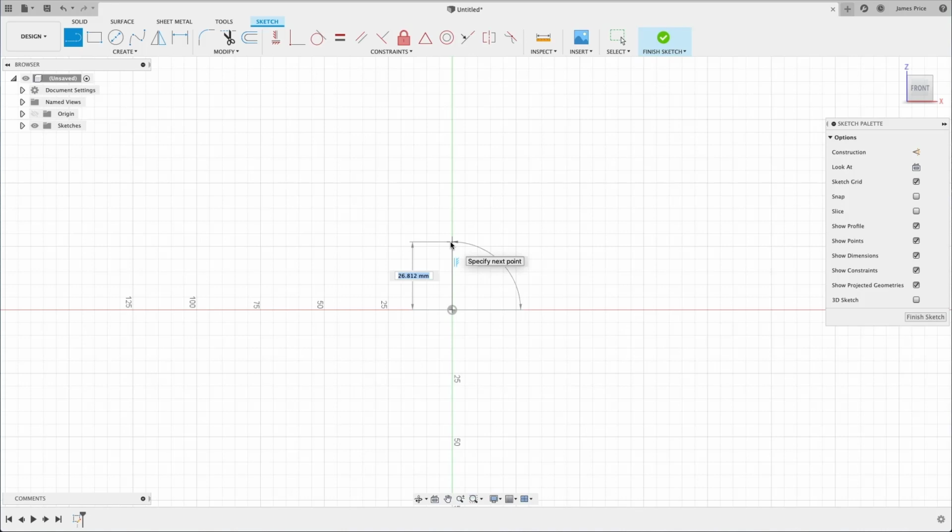Now, create a line that does not snap to the horizontal or vertical at any length and angle by left clicking once you have your position. After you place the second point, you can drag the line out to continue and create more lines. Notice how you can also snap to other sketch features, such as this midpoint here, or creating a perpendicular line. We'll leave this as a single line for now, so click on the green check mark to confirm. You are still in the Create Line mode, so to end it, simply press Escape or Enter on your keyboard.